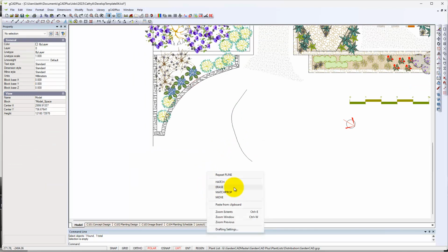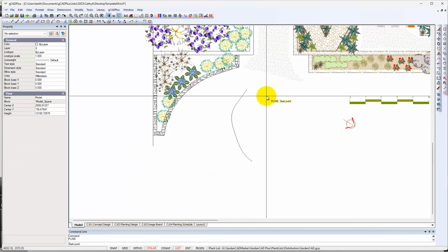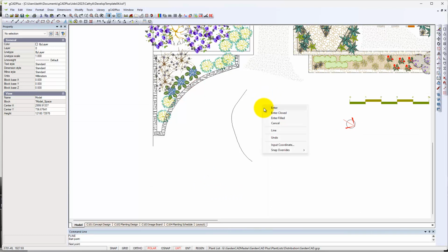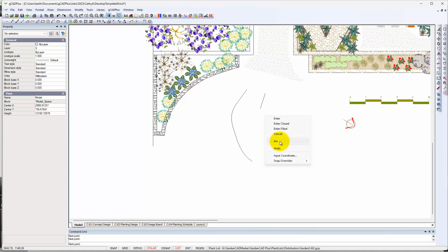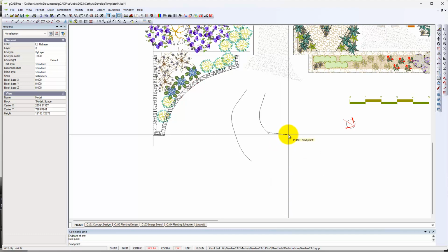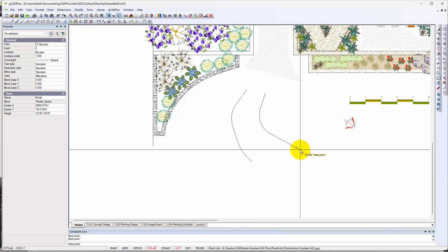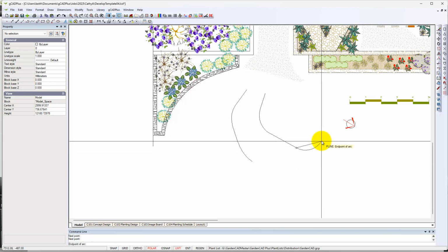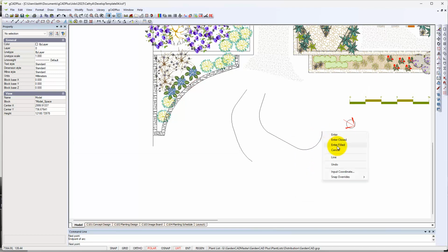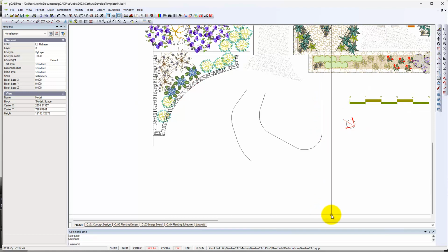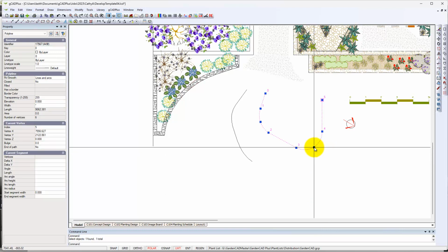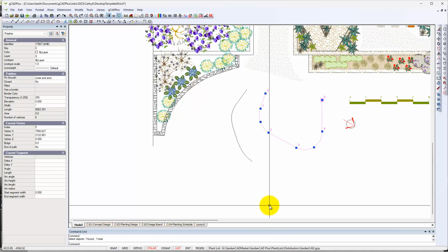and it's done with the option of the polyline. If we repeated that and went from here and then right click and said no, we'll start with a line, and then we'll right click and come with an arc, and then right click and go with a line and head off in that direction, and then another arc, we come back here and then with a line. I hope you can see that the polyline command is really, really powerful. So it's one polyline with those vertices you see there. So it's very easy to control the shape.